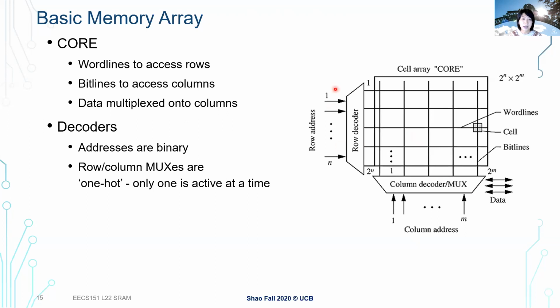We'll think about how we build row and column decoders, especially what the latency constraints are in thinking about the design complexity here. There you have some peripheral logic to specify which row and column we are accessing. And then by setting the word lines and bit lines correctly, we can access each individual SRAM cell, and the data is stored in the cell.